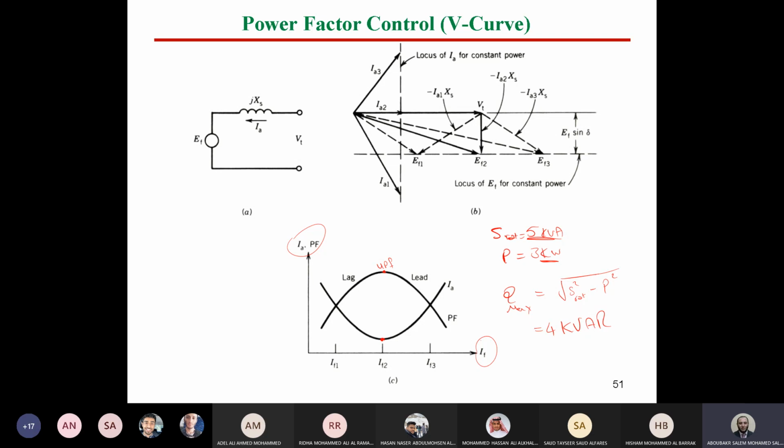Now, if you have a synchronous motor without any load, which means the motor is not used anymore. For instance, in factories they upgrade the machines with their control and so on and leave the old machines. Instead of keeping the synchronous motor on the shelf, you can take this motor and just connect it to the supply without any load and control the excitation. In this case guys, this means you can get the most benefit, which is getting S equal Q. Right or wrong? Where P equals 0 in this case.